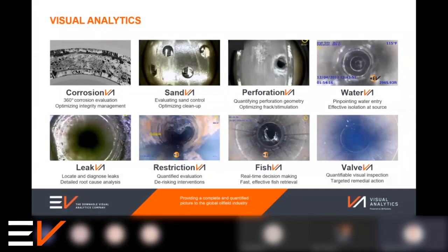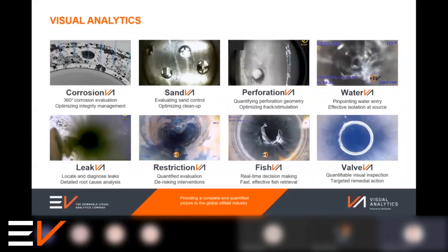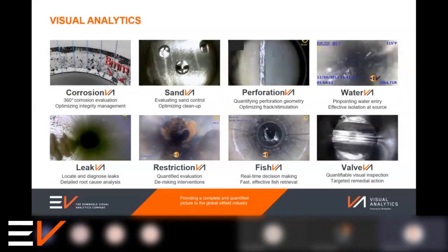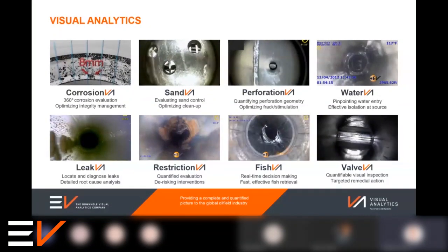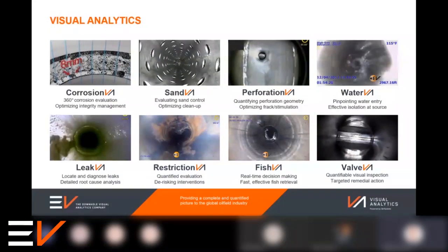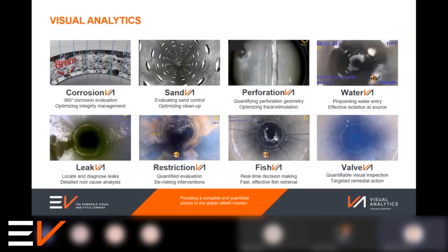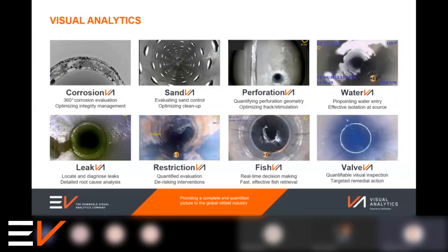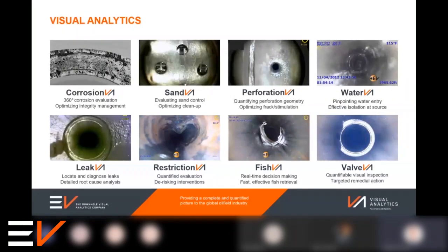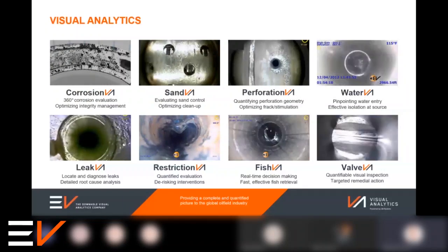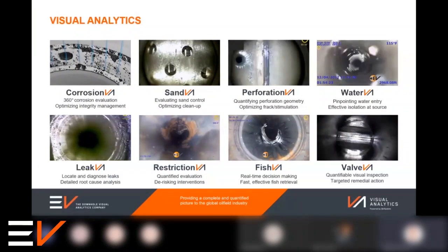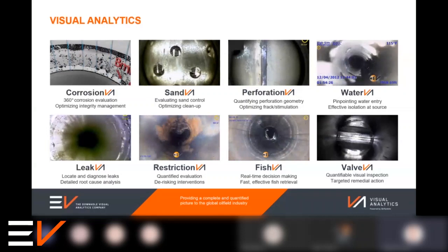But just as a caveat to that, and again with a lot of testing that I did with operators, the erosional effect as the sand does jet through the base holes is phenomenally strong. And we did see quite a large number of perforations that were enlarged with sand ingress. And similarly, on the opposite side of the pipe, you tend to get a washout area as that sand impinged on the opposite face of the pipe. So there were a couple of telltales that we could look at. And I think, again, the video technique is a potentially very strong candidate for assessing the screen performance and condition.